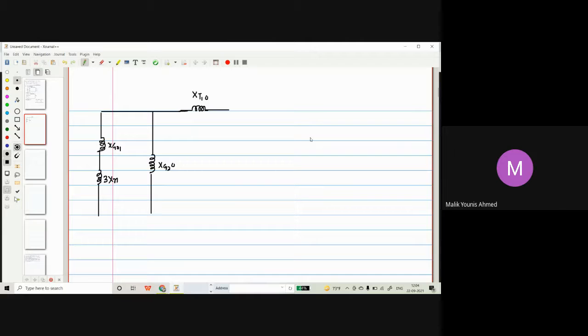Why? Because series switches will close only when the winding is star connected, neutral grounded. Shunt switches will close when it is delta connected. Secondary is delta connected, so we are going to close it here up to ground. Then I will be drawing the ground later on. Now this will be opened here.